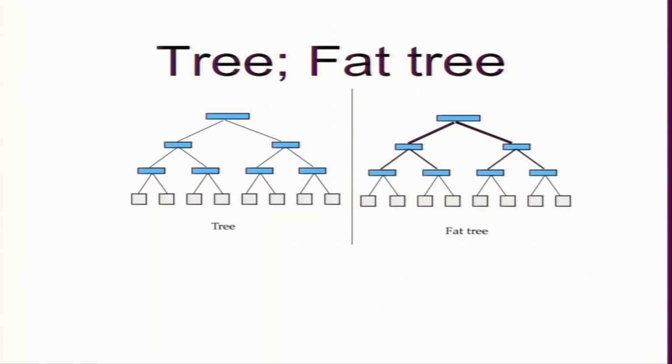Now, there is another architecture called tree. So, please remember this is less than a crossbar, number of links are less, but it can handle more nodes. It is a tree, no, this one is a tree. So, we have 8 nodes and they are connected via a tree. So, I want to go from here to here, what will I do? So, I have to go up that way, that way, that way, this way, this way. So, it has many hops, but we can reach anywhere to anywhere via these connections. If I want to go from here 0 to 1, then I can take just one hop.